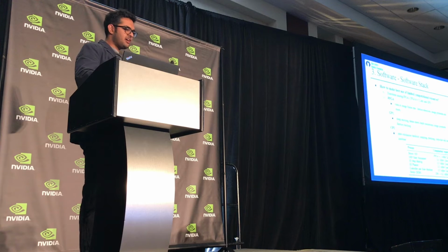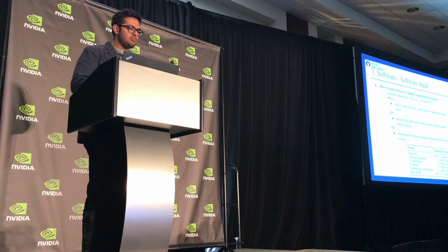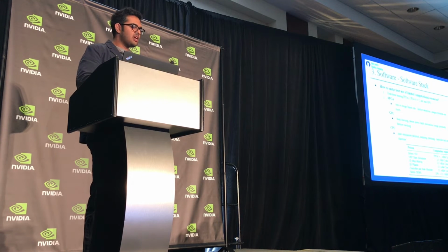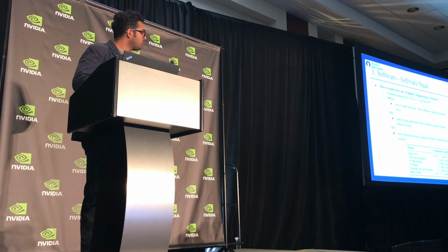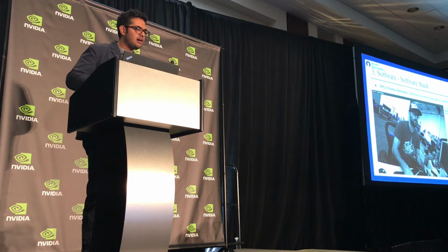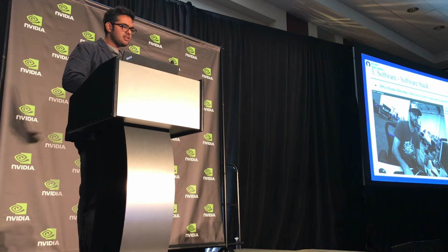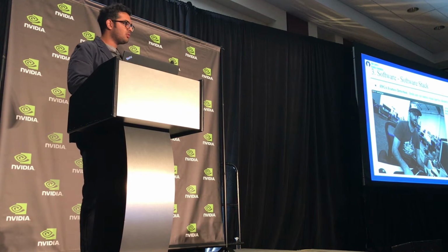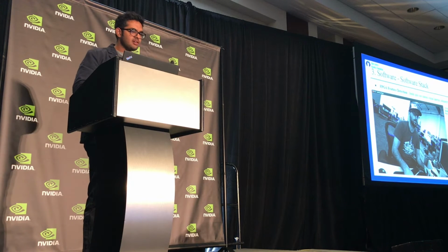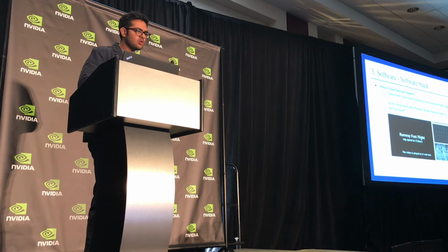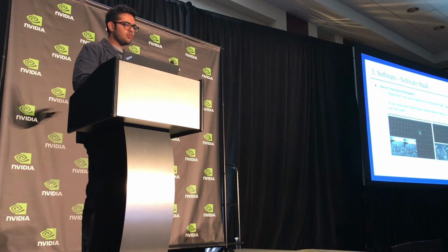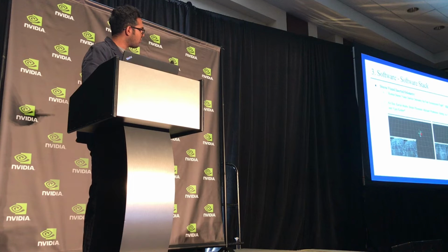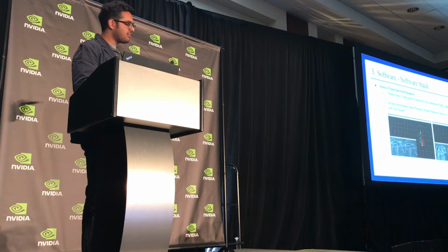So the back end of our state estimation, along with mapping and then the basic controller commands, is done on the CPU. And there's a table of roughly how much computation each of these requires, and the TX2 has been able to do all of this comfortably. So like I said, the FPGA spits out a set of features. That's a picture of Morgan Quigley, who built the Open Vision computer for us. And this is state estimation working at, on the left, a 20 meters per second flight trial, I believe.